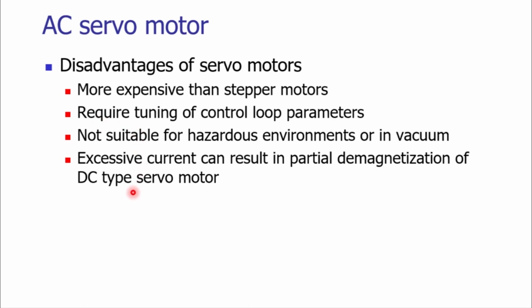In case of excessive current, there may be partial demagnetization of the DC type of servo motor. So if you apply excess current, that may lead to demagnetization of the DC type servo motor. That is one of the limitations.